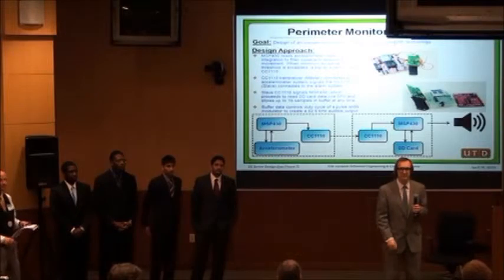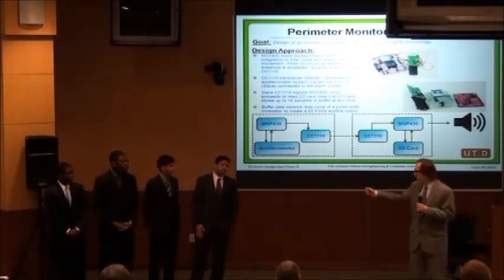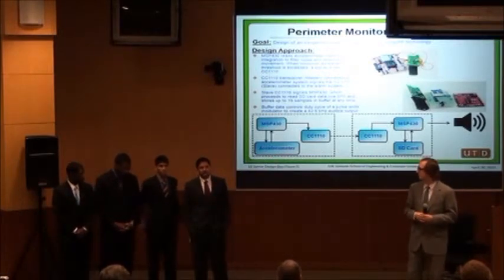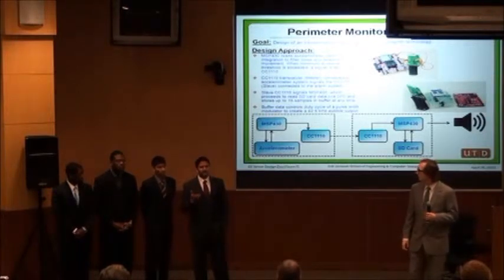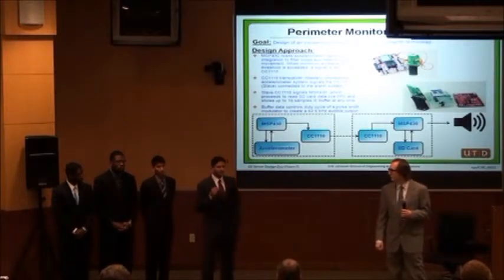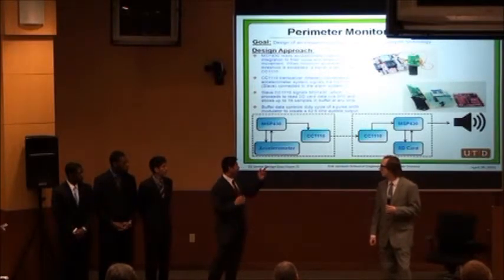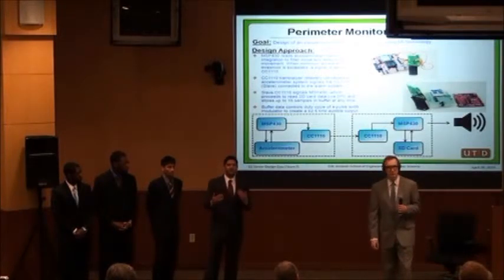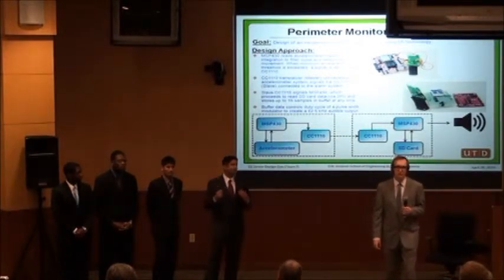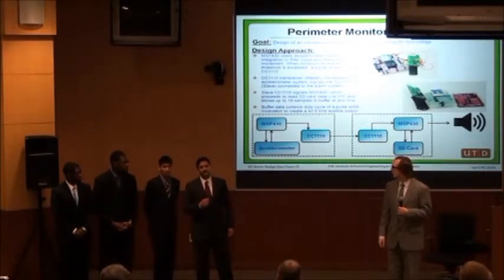You say low maintenance. What about the batteries? So right now it uses about 33 milliwatts. If we play around with some of the jumpers and stuff, we can get about 660 microwatts. But right now the software constantly runs an interrupt, because we're reading the alarm tone from an SD card and we're constantly sampling the accelerometer at a very high frequency. So I'm sure we can optimize the code so that it can run off AA batteries. But right now, if you want it battery powered, you probably need a lithium-ion battery or something.